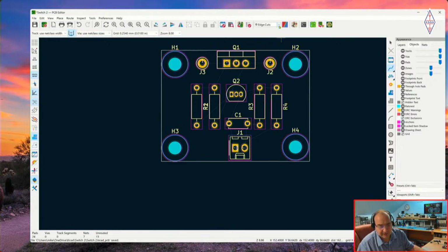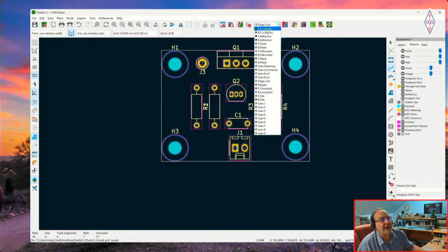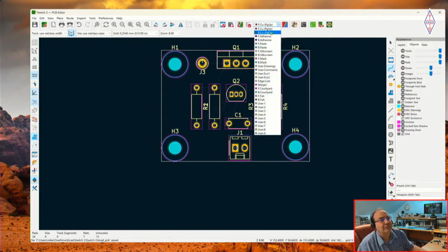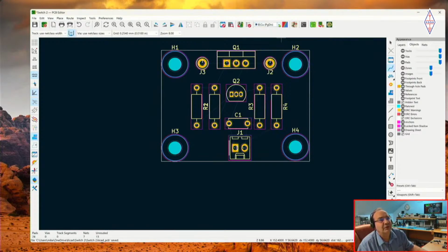Now let's talk about tracks. So PCB has 2 layers. One called front copper, which is coloured standard in red, and one called bottom copper, which is typically coloured in blue on the screen. So you're looking down from above, down on the PCB. I'm going to do most of the wiring on the top of the PCB, and there's a reason for that.